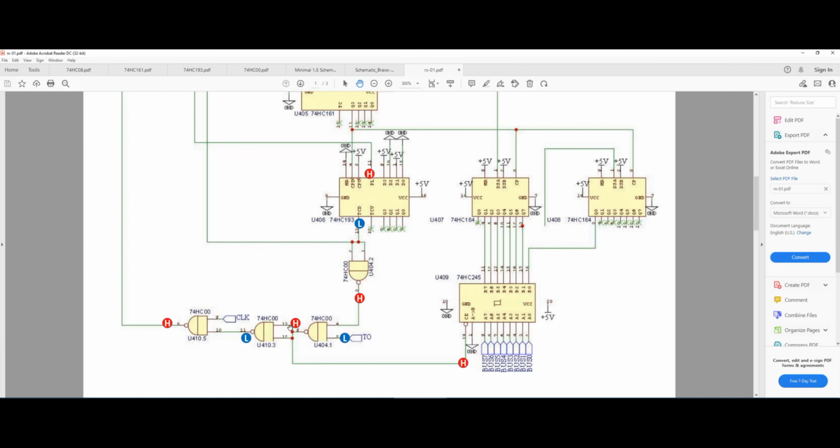And again, when both signals are high in this NAND gate, the output will be low. And regardless, of course, of the clock signal coming to another NAND gate here, and regardless of the status of this clock, because one of the legs is low, the output of this final NAND gate is high.